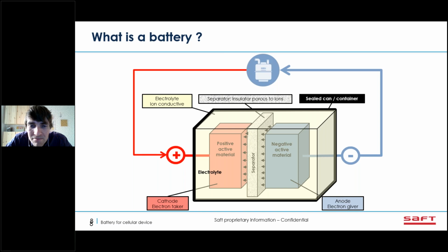With primary chemistries, the only solution is to have several cells in series. So a 2S battery pack: you connect 2 cells in series, and here you will have a nominal voltage closer to 6 volts or 7.2 volts, depending on the chemistry inside the pack. But in this case, you need to manage the maximum voltage of the battery at electronic level, so you need to find other ways. But a 3.3 volt minimum voltage with only one cell, even at room temperature, will not work for a long time.